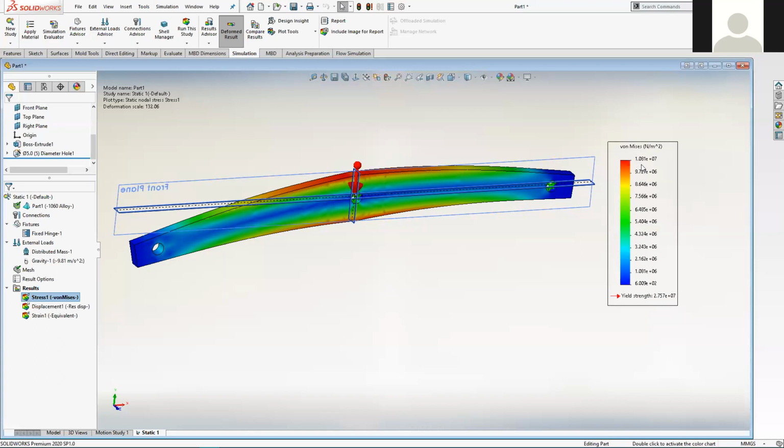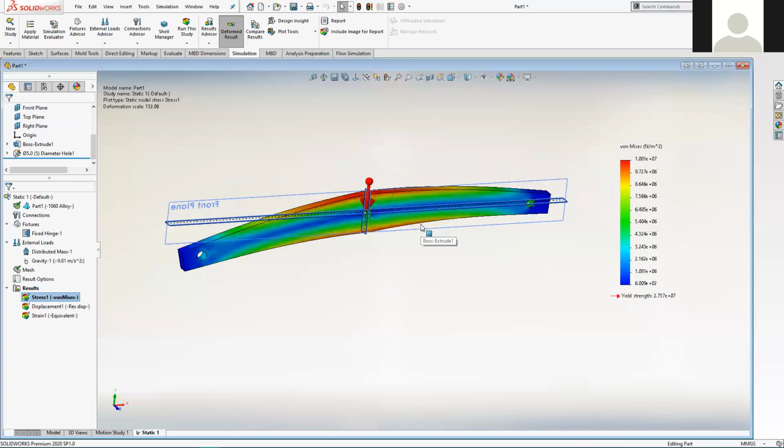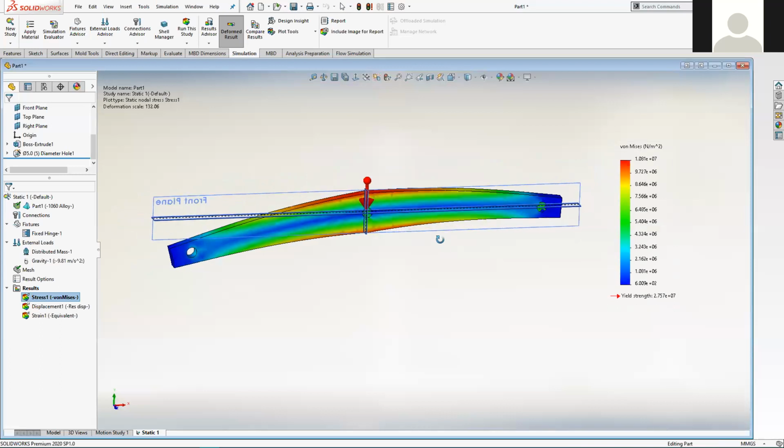We haven't tackled how much of a factor of safety it's got, because I would argue it's actually still running a little bit close for my liking, even though it's down below half. But certainly for this exercise, we're going to work to the yield point rather than working to a factor of safety, just because it simplifies the exercise slightly.